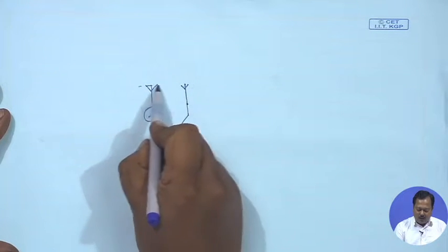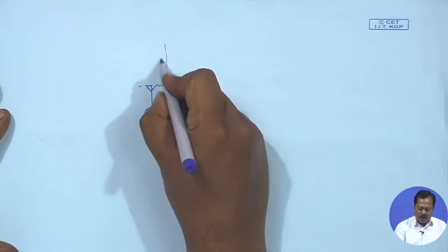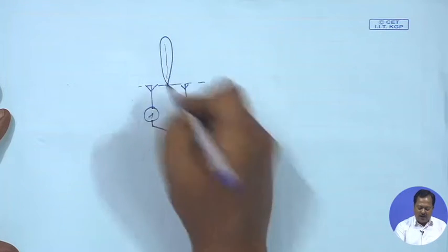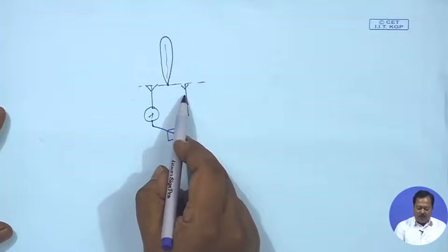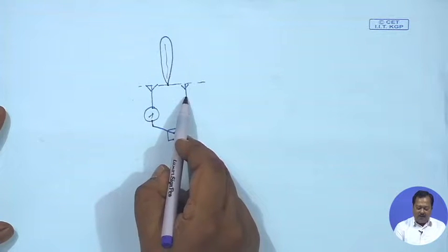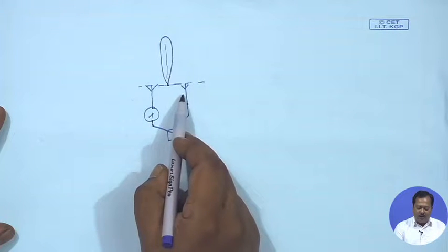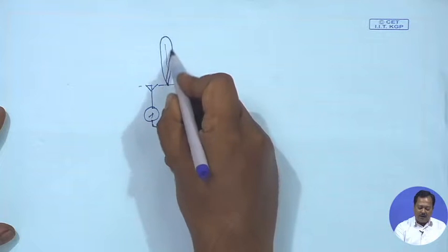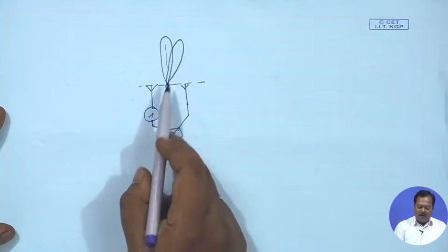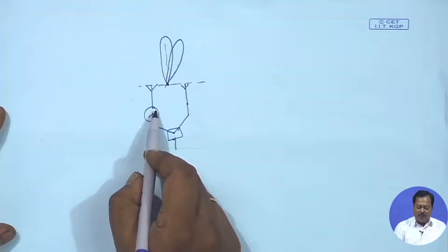Now, the resultant beam direction is in broadside direction when the phase difference between the two antenna feeds is 0. Now, if we introduce a phase shift between these two antennas, then the beam direction will change, and this new beam direction depends on the phase shift value.